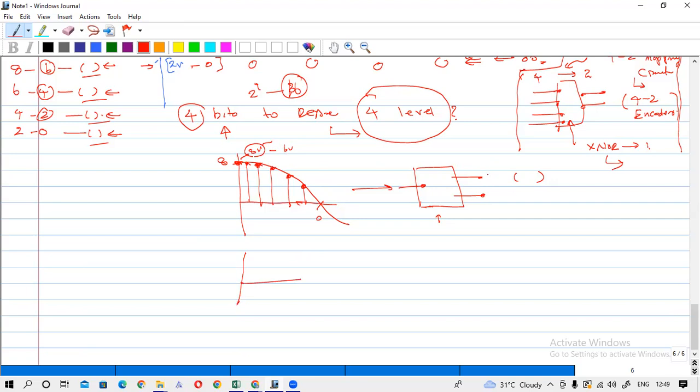So we have some bits here. If you consider this voltage level, maybe it is less than 6, or greater than 6. If it is greater than 6, you have to quantize them up to 6. If it is less than 6, you can quantize them to 6. Then voltage 6 also you can encode. So for other voltage levels you can consider, you have to quantize it to the encodable value, then you can encode it to the binary value.